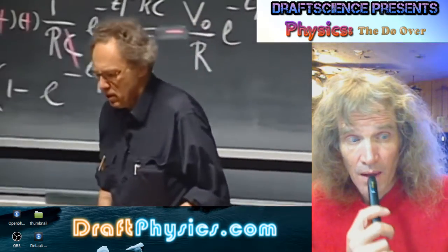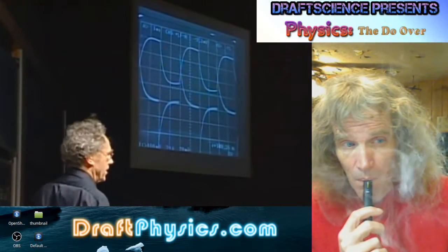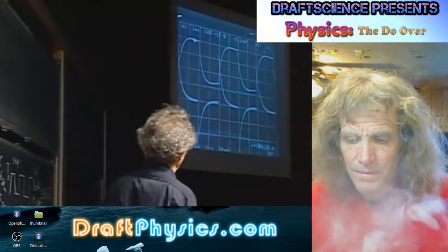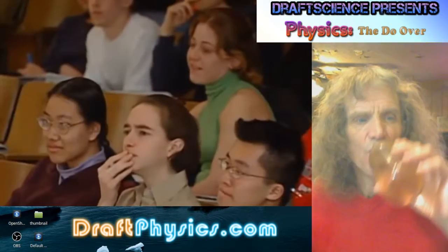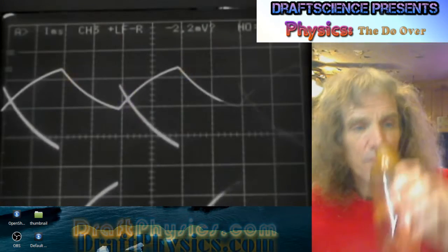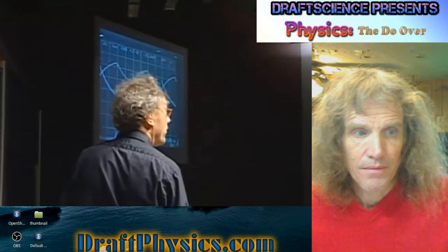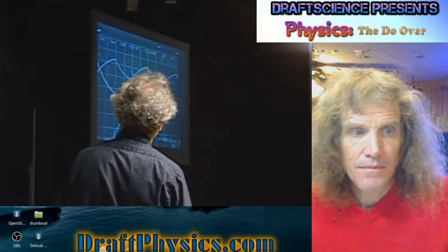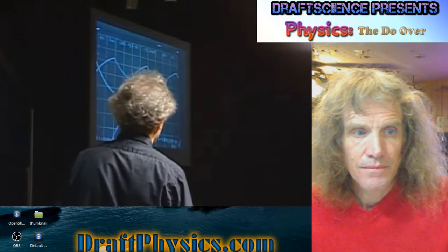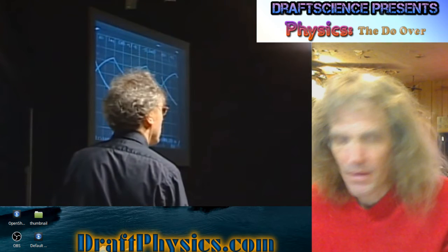What I can do now is to increase my capacitance by, for instance, a factor of 5. So that would change my RC time to 3 milliseconds. So now there is no way that the capacitor can become fully charged in the 4 milliseconds that it has. And you will see that indeed, if I make this 0.5 microfarad, the capacitor has not enough time to get fully charged. And so here you begin to discharge. Notice also that the current doesn't reach 0, for the same reason that the capacitor doesn't get fully charged.